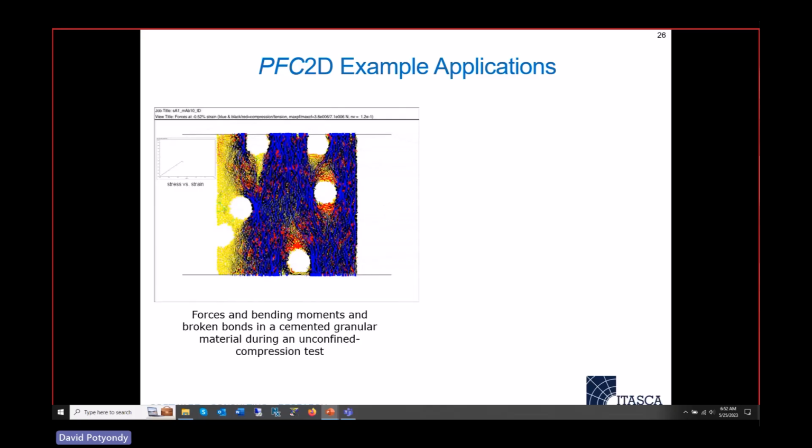Remarkably, if you glue together an isotropic packed set of discs or spheres, and you put infinite strength on the glue and apply all sorts of deformation to it, lo and behold, it will behave like a linear elastic isotropic body. But then, what's also interesting, it will begin to fragment and break just like a rock will break. And of course, its properties will change as that happens.